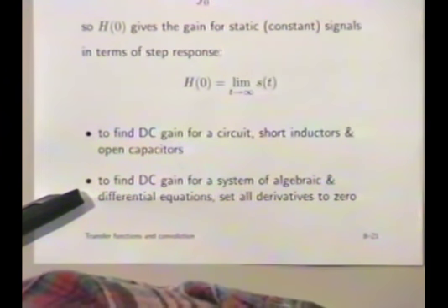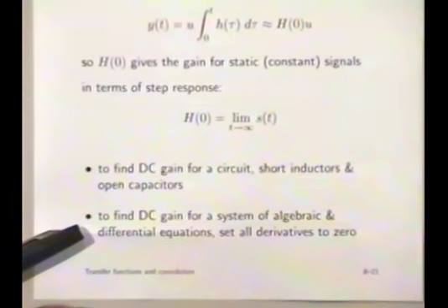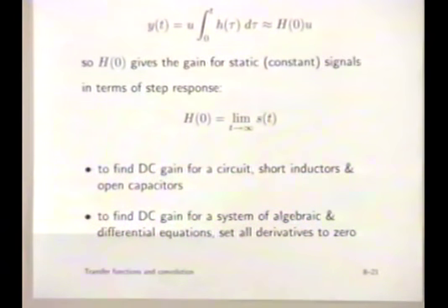It has to be 0, period. Because in fact, the input to the integrator is the derivative of its output. If the output is constant, the input is 0. If you have anything non-zero going into an integrator, the output will ramp. But that's not allowed. It's static. So in a big block diagram, you simply take every integrator and make the input 0. And this will give you the static steady state or DC analysis of it.